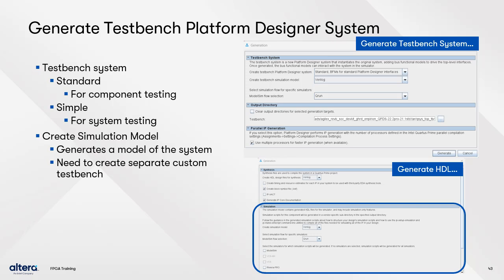This is most useful for component testing. If you choose to create a simple system, only clock and reset BFMs will be added. This is more suitable for system testing. For test benches, you also have the option to generate for either Verilog or VHDL.